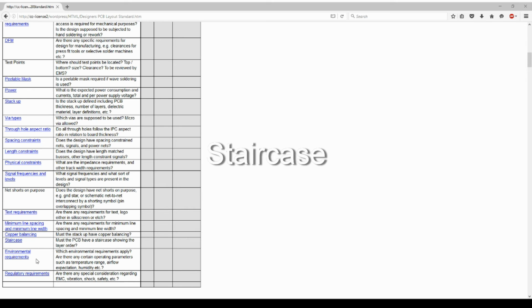Knowing what requirements we may see from EMC, from mechanical testing and so on, would of course give us a good idea of how to do a lot of things. And obviously, if we have customers coming up with tough EMC requirements, that may lead to adjusting some of the clearance rules, or maybe the whole stack up should be changed. Other strategic decisions may be changed due to such requirements.